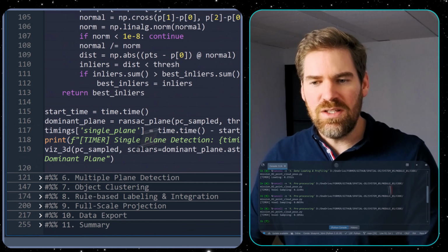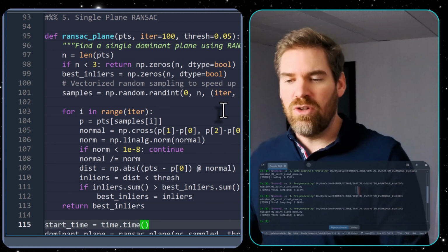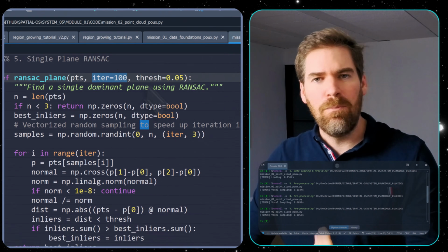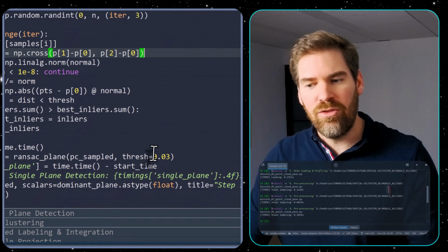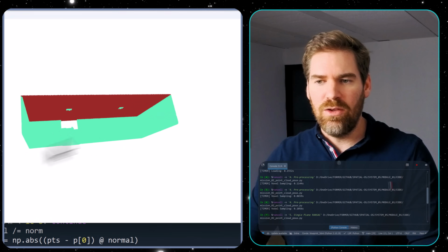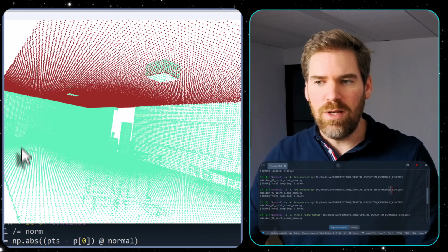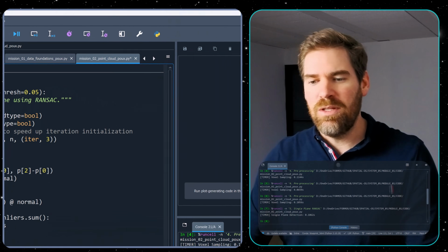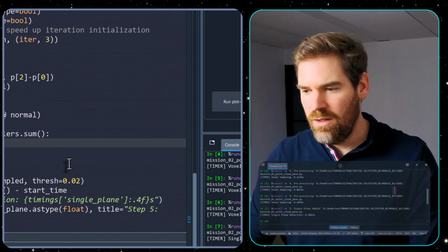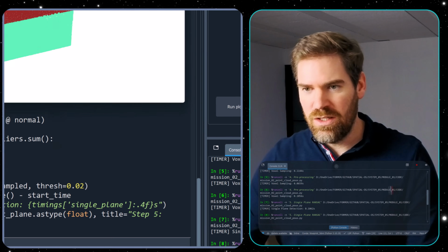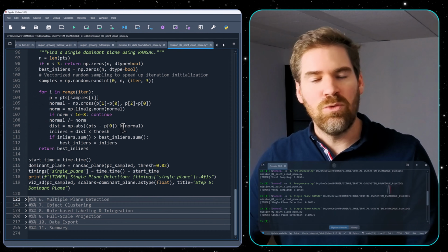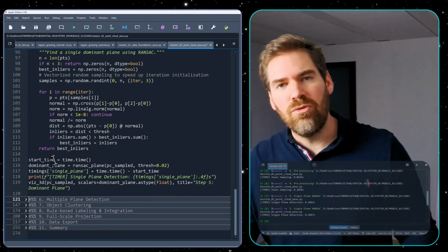Now what I do, this is stage 5, we'll use a shape recognition algorithm, specifically RANSAC as we mentioned. So we have a number of iterations where we will try to find the plane, and we have a threshold that I push to 3 centimeters to retrieve the plane. So if I use it like this, we retrieve one main plane, that is the ceiling. It's deterministic, so if I were to change the threshold here and re-execute, we still have the plane.